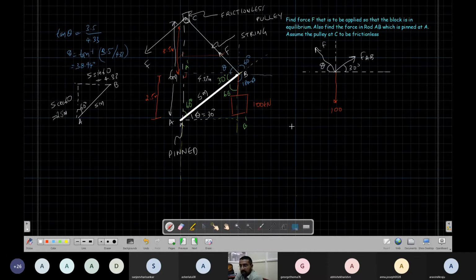Okay. So it is in equilibrium, as B is in equilibrium. So this is what I said yesterday. Method of projections, components. Okay, equilibrium. Summation of forces, all the x components of forces should equal 0, and summation of all the y components should be equal to 0. With the x component, F_AB cos 30 degrees in the positive direction. So x in this direction is positive, y in this direction is positive. This is positive, this is negative, this is positive, this is negative.